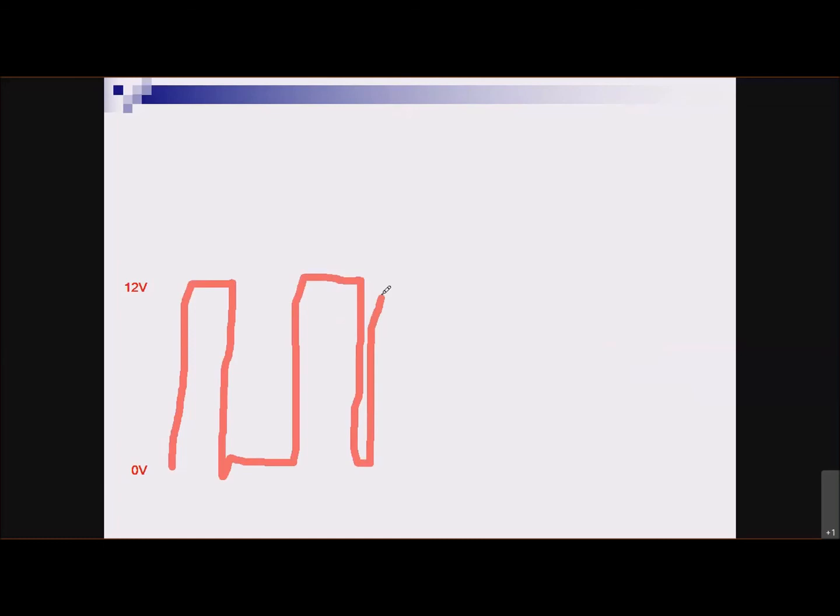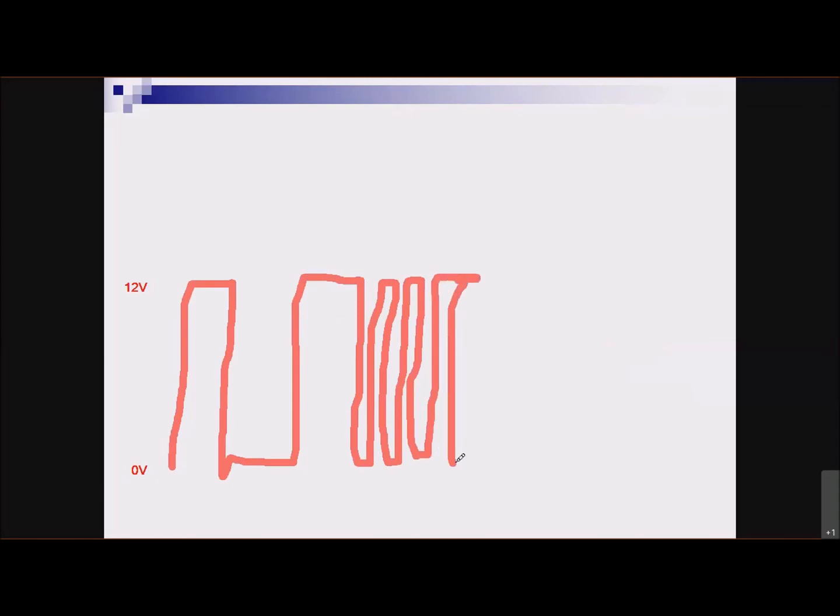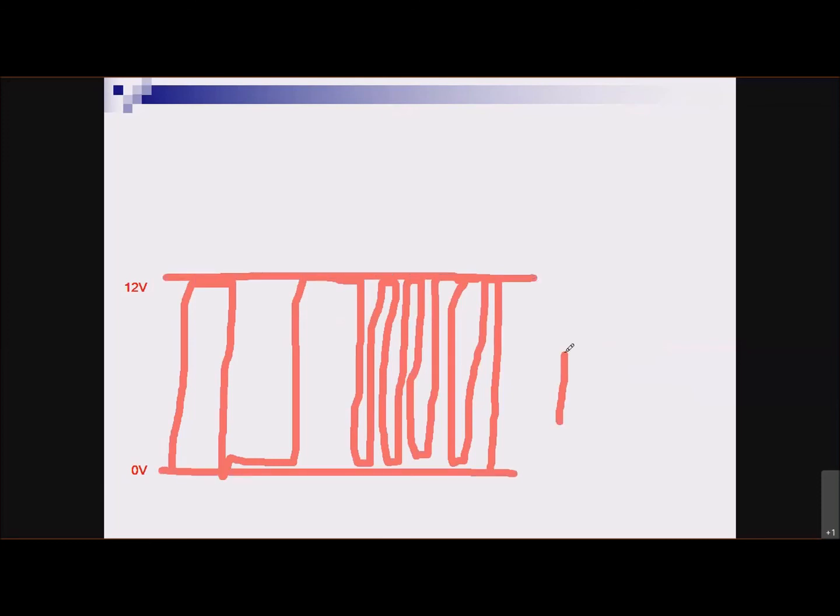The frequency type, which they look the same on the outside, so you never know what you're going to get. The frequency type is a square wave. It turns on, it turns off, it turns on, it turns off. And what happens when you hit the gas is that frequency gets much, much higher. So the on and offs come much closer together. This is really a horrible drawing, I know. It's hard to draw with a mouse when you're not used to it. So the frequency increases, and the voltage obviously is still 12 and 0. So voltage doesn't change at all. It's just flipping up and down more rapidly with higher airflow than it is with less airflow.